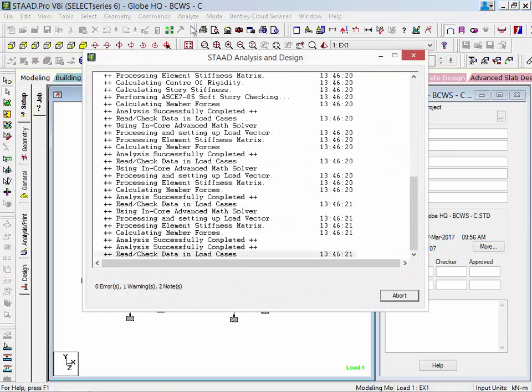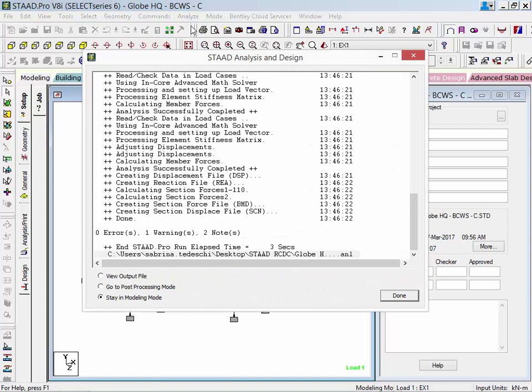Now, as you look at your sample model, you'll probably notice that no slabs have actually been created in STAAD Pro. The STAAD Advanced Concrete Designer, the RCDC, will read the beam and column geometry from STAAD files. From this geometry, it will identify all of the enclosed regions within the geometry, which could be slabs. This would include actual cutouts and slab areas. The RCDC also works out the spanning type, either one-way, two-way, or cantilevered slabs, and the continuity of each and every slab will be reported.